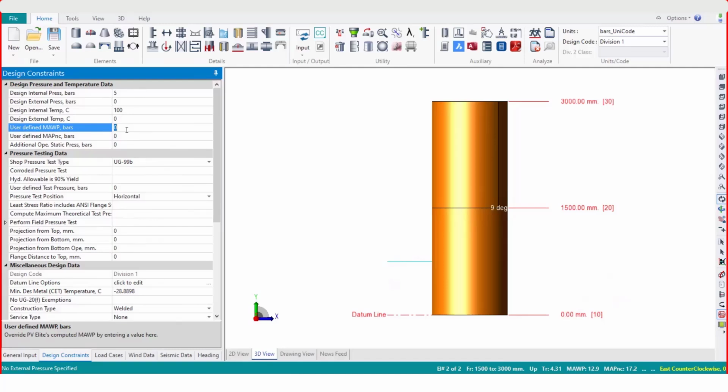The equipment already has a MAWP, let's say 8 bar. Now the new bonnet you have created has a MAWP of 15 bar. So are you going to do the hydro for that entire equipment at 15 bar? No. It should be based upon the lowest component MAWP, isn't it? So let's say the lowest component which is already in service is at 8 bar. Your new component that you designed should have MAWP equal to 8 bar. So there we can put it over here.